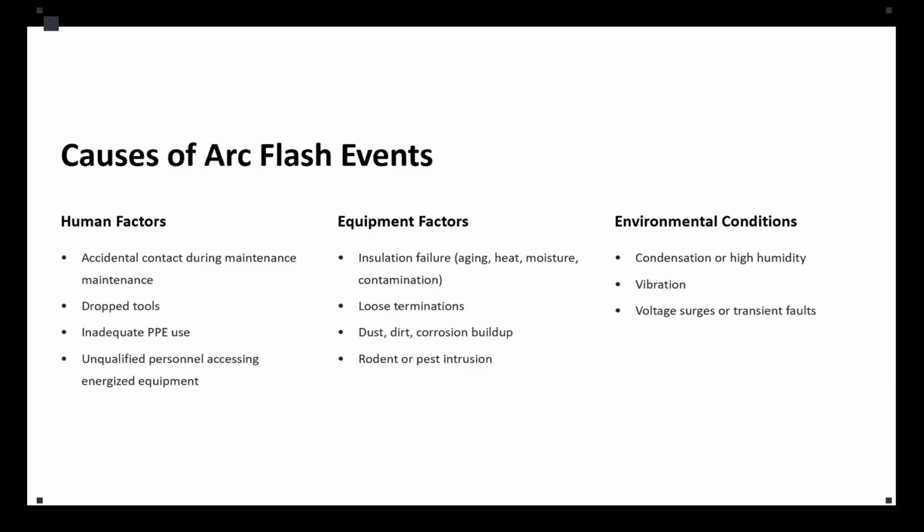That localized heating can melt the insulation or deform the terminals, and it could cause phase-to-phase or phase-to-ground faults, which can initiate an arc flash.